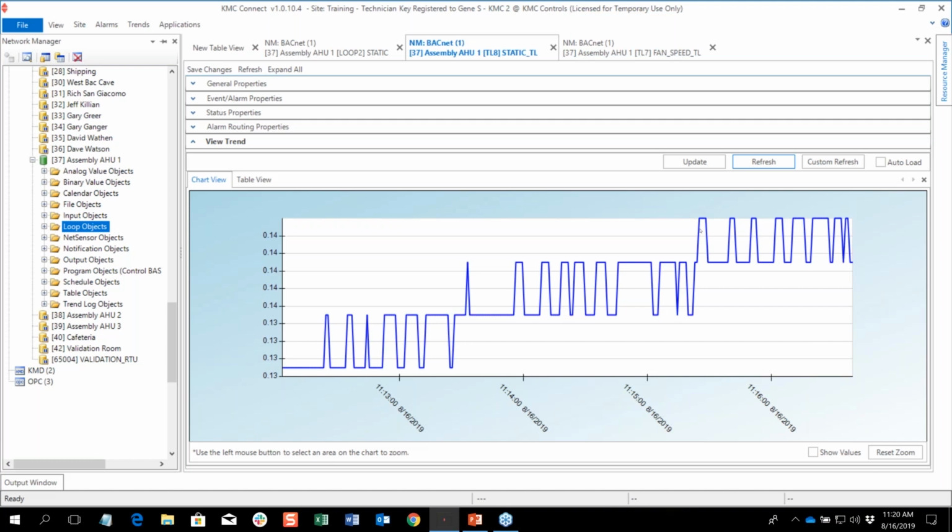It's usually only used for slow moving loops. So think of a room temperature or a mixed air. And I'll say for most systems, proportional auto tuning is where I would point you first. Experiment with it. Certainly give us some feedback. When you try to do PI, there's a little too much moving in that system if you don't have it set up right. So I find it's faster to tune the integral a traditional way like Gene showed us, but maybe I would use the auto tune. If I want to start playing with the auto tune, then I would do that on proportional only.